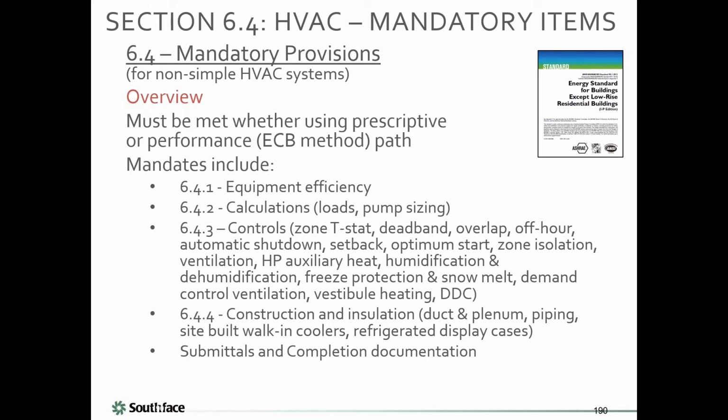First of all, there are always what's called mandatory provisions or mandatory requirements. These have to be complied with. Examples: load calculations, pump sizing, and lots of control capability. These are things we've already talked about: automatic setback, optimum start, and so on.